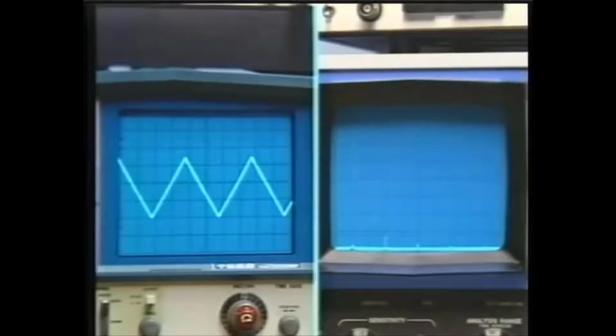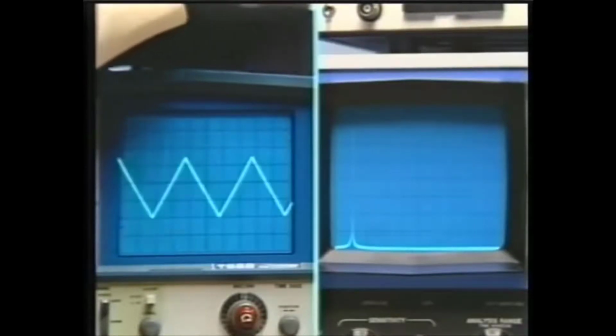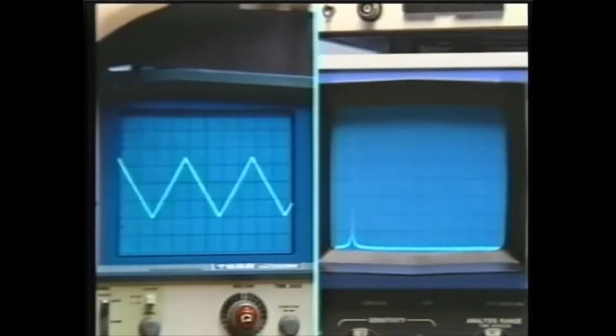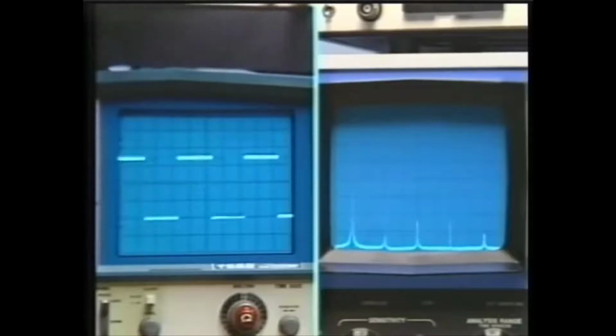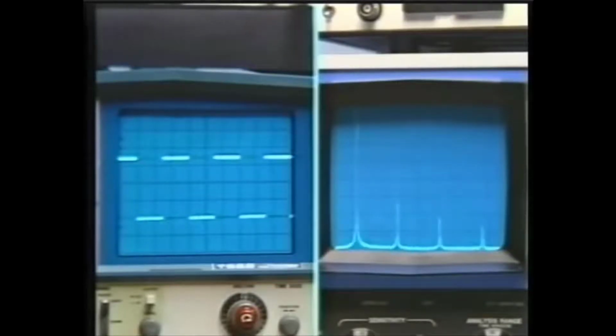And maybe just to emphasize the point, we can show the sine wave again and the square wave again. We'll go through from the most bland to the richer to the richest. It's really interesting and dramatic to see the harmonics pop in. While we're at the square wave, let me fiddle with the frequency of the square wave, and we can see the duality of the time and frequency domains. That is, as you compress things in the time domain, going to a higher frequency square wave, the harmonics wander further away from each other.